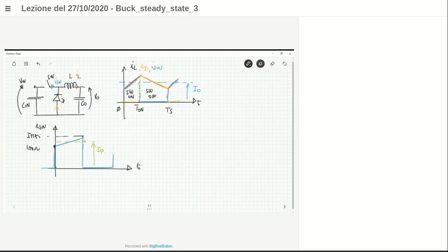Okay. If you use a MOSFET as a switch, then you have to evaluate the root mean square current flowing through the MOSFET, because the conduction loss depends on this current. Of course, there exist some very accurate expressions. Okay, I adopted an approximation which is called the flat top approximation.